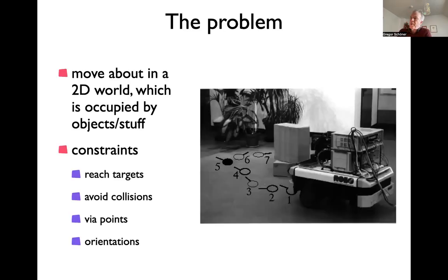So let me first go back to defining what is meant by vehicle motion planning. It's planning of the paths of vehicles in the plane, in a 2D world. Of course, for cars and so on there could be elevations in 3D, but locally it is always 2D. So it's about avoiding obstacles, anything that sticks out from the 2D surface at any moment in time, and going toward targets. Under some conditions, there are additional constraints like planning a path that goes through particular points or that achieves particular orientations. I'll generalize that over the lecture and look at things like docking, controlling orientation in some way, and maybe moving along a path, for instance, staying on a road and things like that.